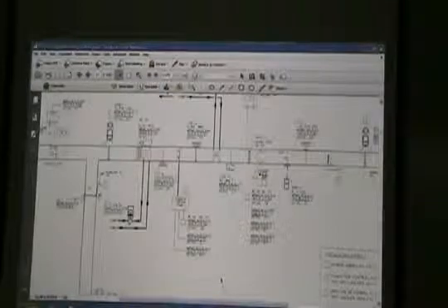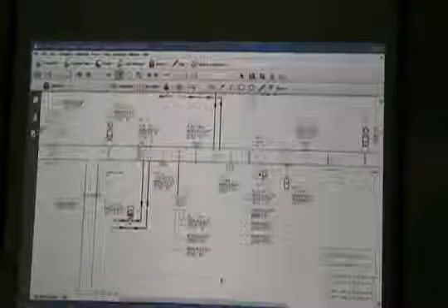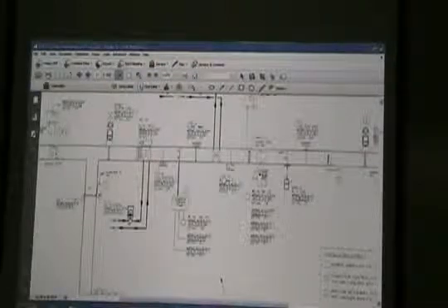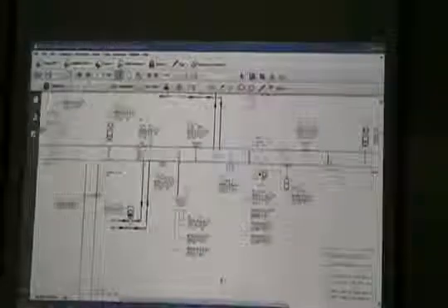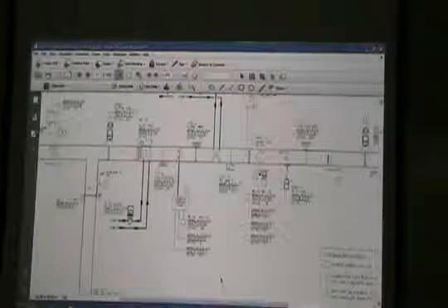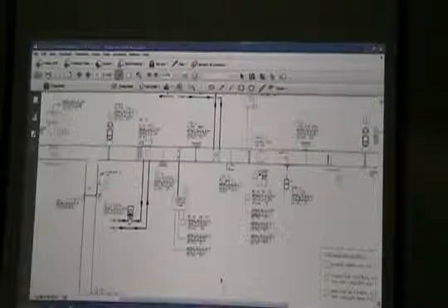Depending on the volume of outside air, we haven't talked about that, there's the airflow measuring station. And there'll be a damper behind here associated with that to control the amount of outside air. We haven't got to it in the sequence. But that device right there needs to be right here, or we need to add a device right here to really give us mixed air temperature, which is what the engineer is asking for.